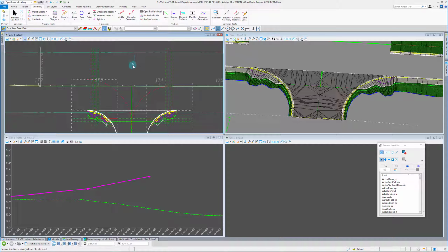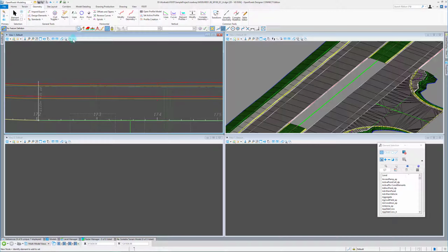So what we'll do first is go into the end condition left file and make a little space for our curb ramp civil cells in our existing corridor. Drop our civil cells in there and then stitch everything back up. Alright, so now we're in our end condition left file and we can start setting up to draw our curb ramps in here.